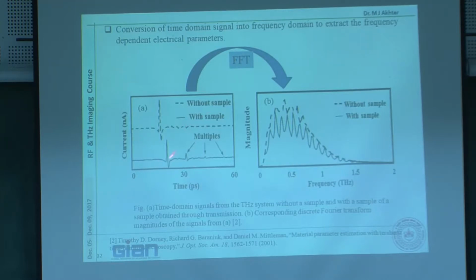Terahertz, this again is a very important aspect: if you want to design a system using terahertz, there are two approaches. One is that if you buy a network analyzer, they give you multipliers that work up to say 1.1 terahertz. The concept is simple: you have a normal network analyzer, you go on multiplying until you get 1 terahertz. This is one approach, and it is usually used by most engineering institutes.